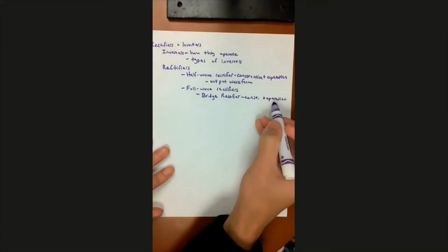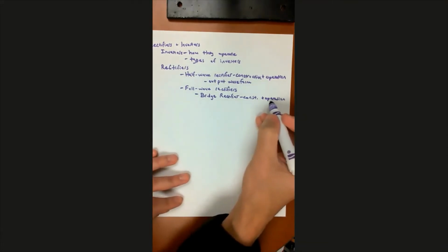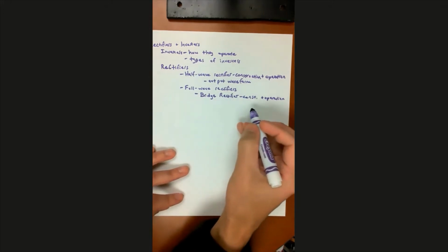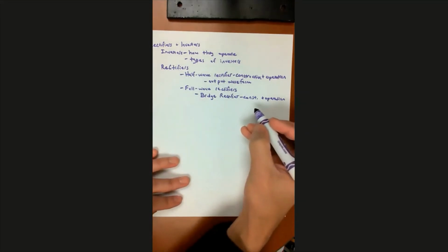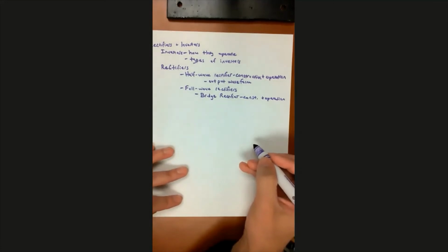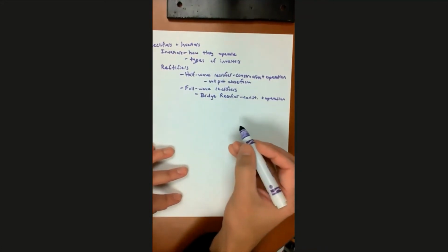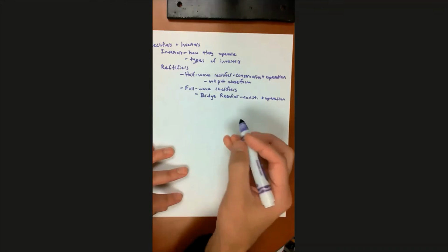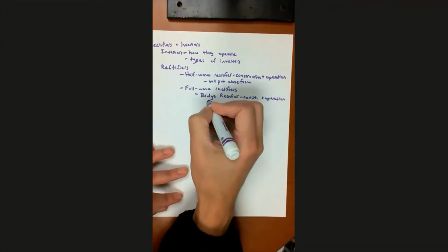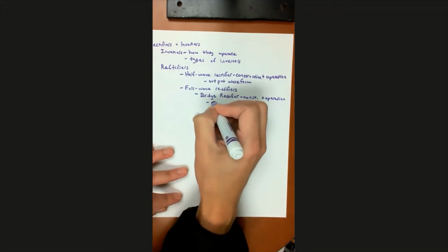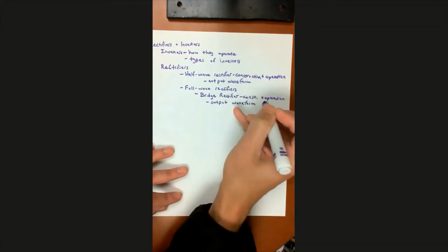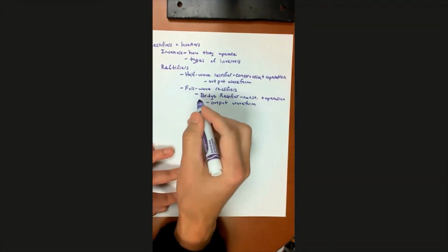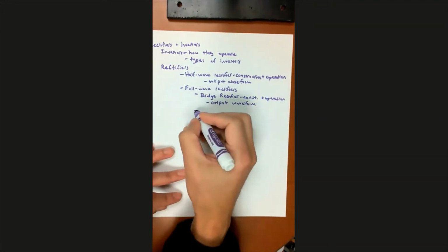There's, I think, a pretty good description of its operation in the lab manual. So make sure you read through that and understand how this works in both the positive and the negative half cycles. The current flow is not going through the same path in the positive half cycle as it is in the negative half cycle. So you should understand how this bridge rectifier works. And same thing up here, the output waveform. So for a bridge rectifier, you should know what the output waveform looks like.